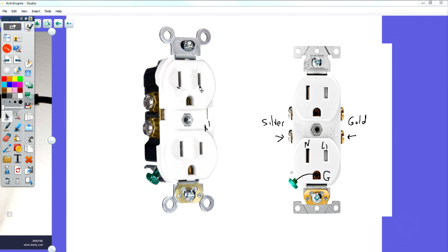Okay? Now, the thing is that if you flip it upside down, the drill's going to work just the same because it's AC voltage and it does not change the way the drill motor goes. But what happens is the power's backwards. It'll still work normal, but safety-wise, it will not be safe. That it could harm you because there's voltage at the motor all the time.